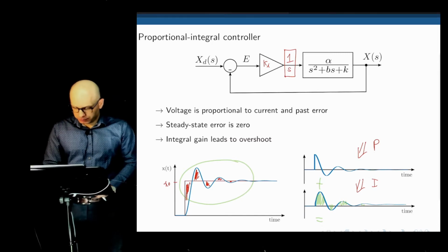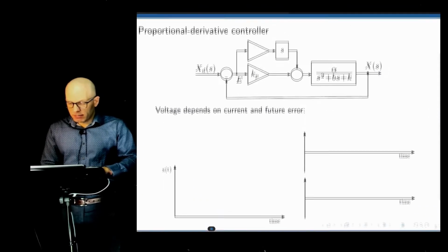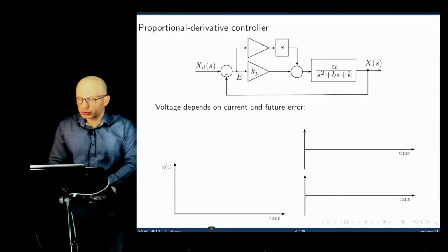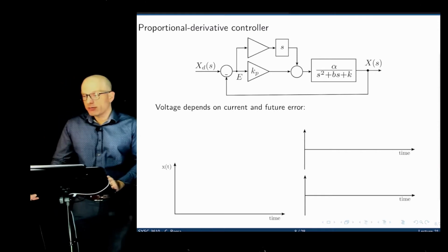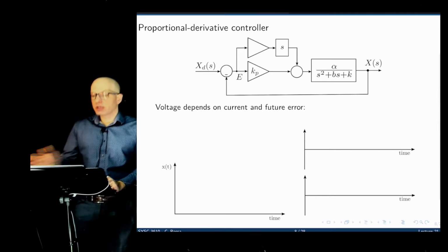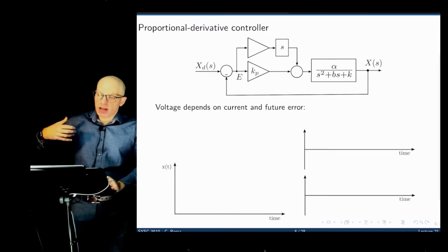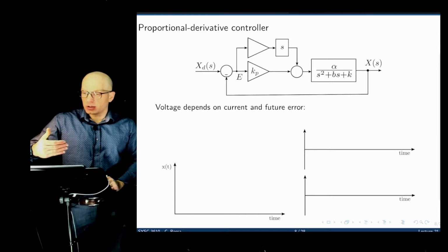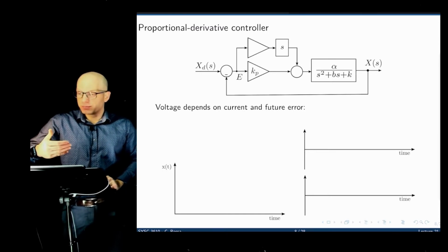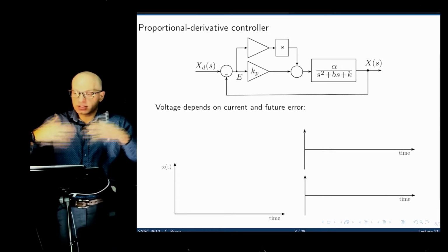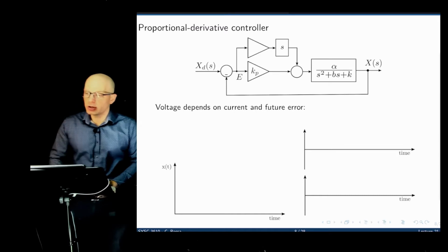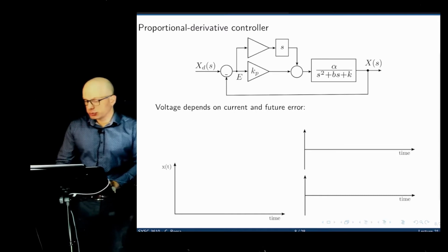that position. And that's the main limitation of the integral controller: this extra energy provided to the plant will eventually make it overshoot. We will accelerate, the mass has some inertia, and once we reach x0, the desired point, the proportional controller can turn off, but now the mass has some inertia, so it'll keep going, right? And we'll keep going and overshoot.